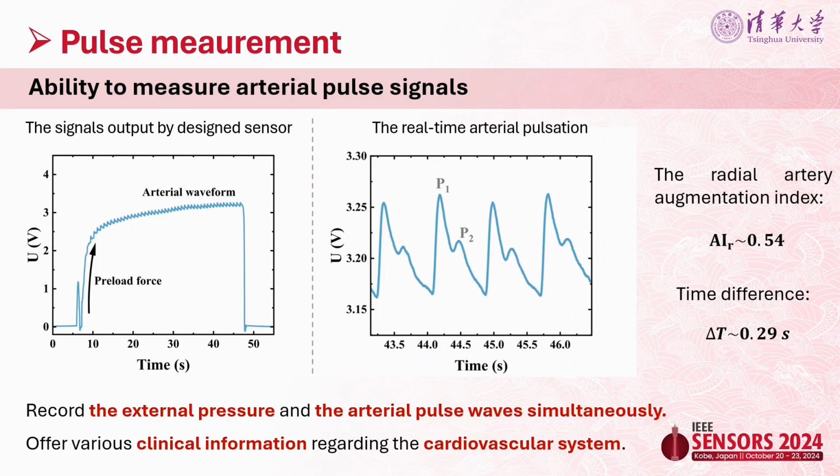After integrating the piezoelectric sensor with TFT, we tested its ability to measure arterial pulse signals. In our test, a healthy volunteer in her late 20s put her right wrist on the device, and the external pressure and the arterial pulse waves were recorded simultaneously. And the right picture is the enlarged view of the pulse waves, exhibiting the device's ability to capture the subtle waves.